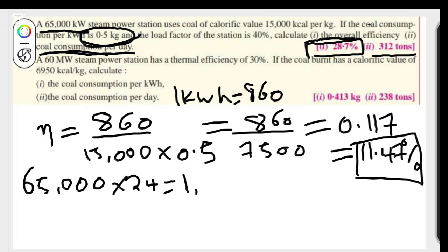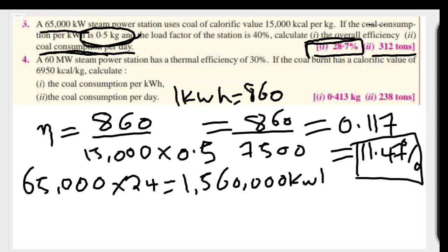After then I'll get almost 1,560,000 kilowatt hour. Don't forget I have the load factor of 40%. So I have to multiply it by 0.4.